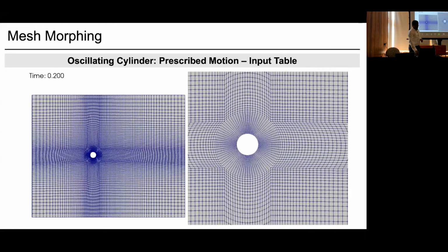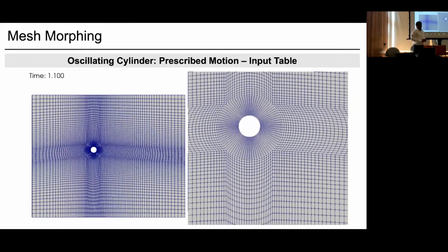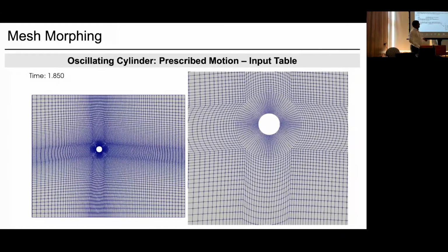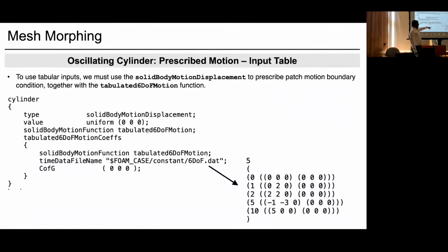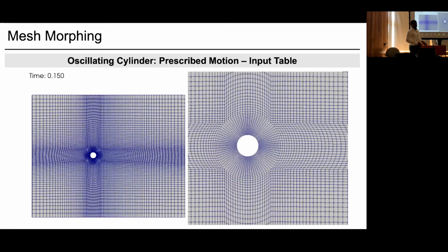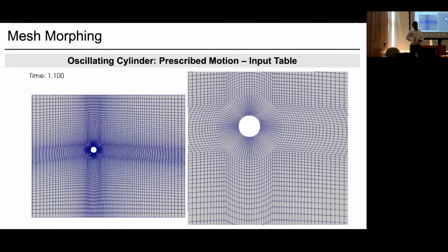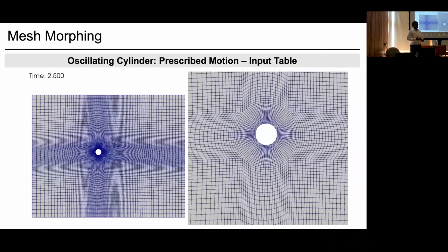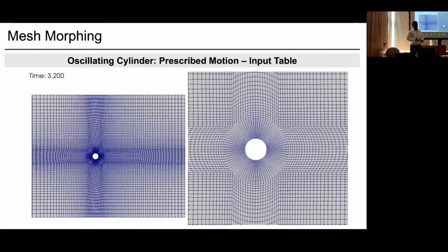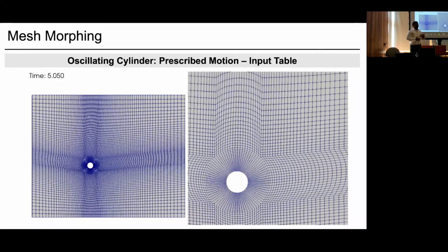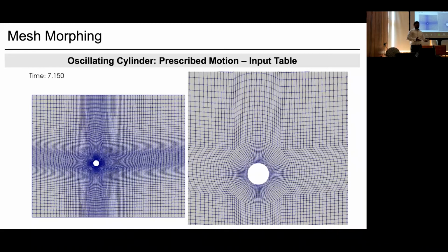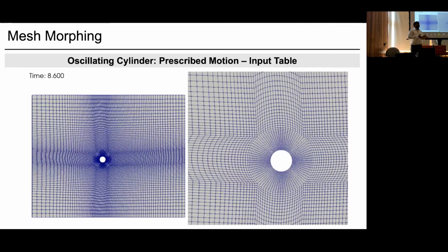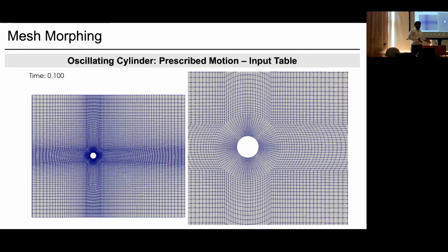So this is an example where, if you notice this function, I have changed the table in such a way that the body goes upward and then goes horizontally. And if you simulate that, you would see something like this, right? This is a very useful function of OpenFOAM, where you might want to simulate a moving body problem which does not fall under the very intuitive periodic functions.